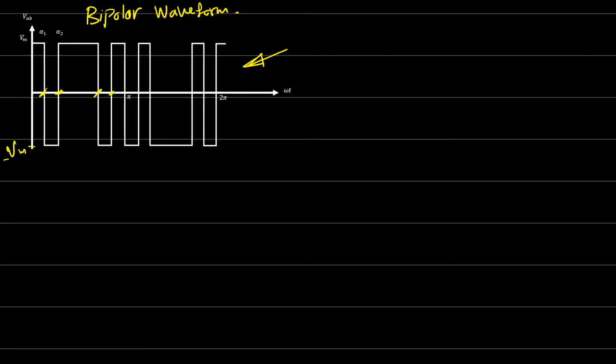And because it's a symmetrical waveform, we can see that A0 and An are equal to zero. Okay, at the end we have Bn, right? Bn also has even harmonics that cancel each other. Now we can say that Bn is equal to how much? 4V maximum over pi.